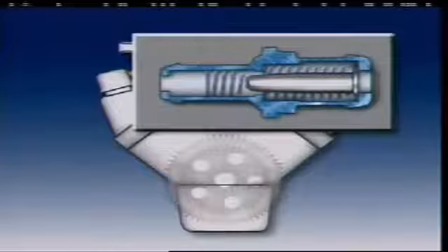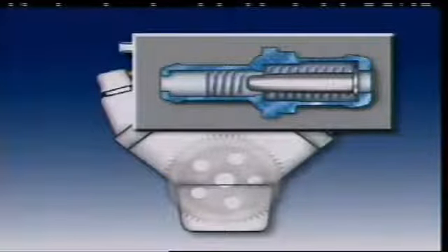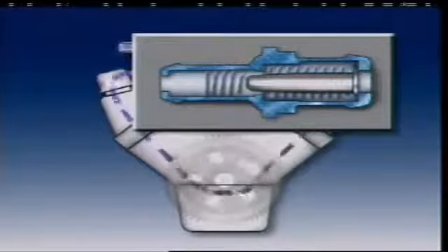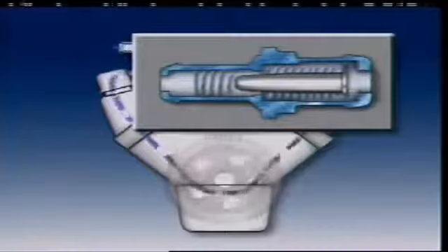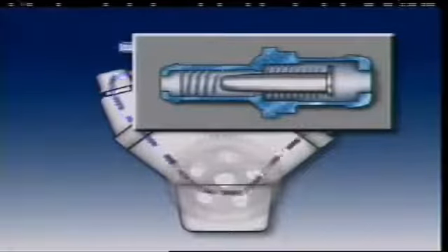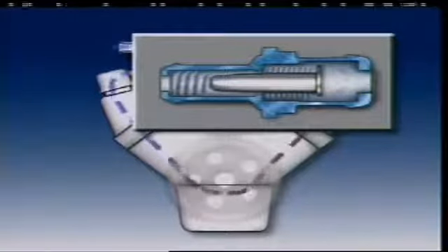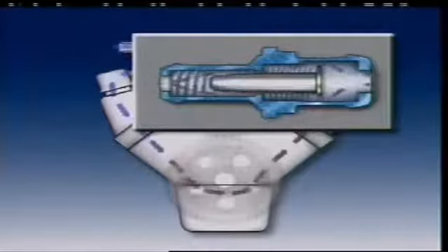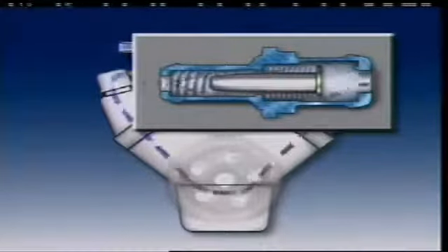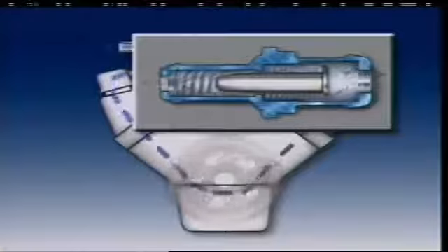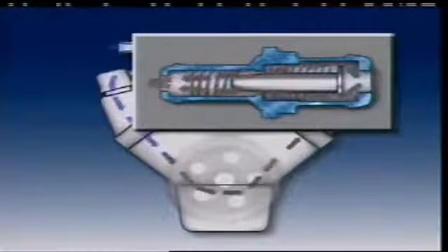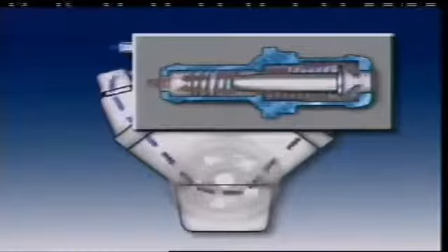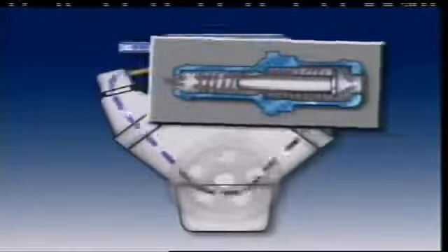With the engine off, the valve is closed and air cannot enter the inlet manifold. This allows the engine to start. At idle, low pressure in the manifold draws the valve to the other end of the body. This lets a small, measured amount of vapor pass the valve. At wider throttle openings, the valve plunger position allows maximum flow through the body, which gives maximum crankcase ventilation.